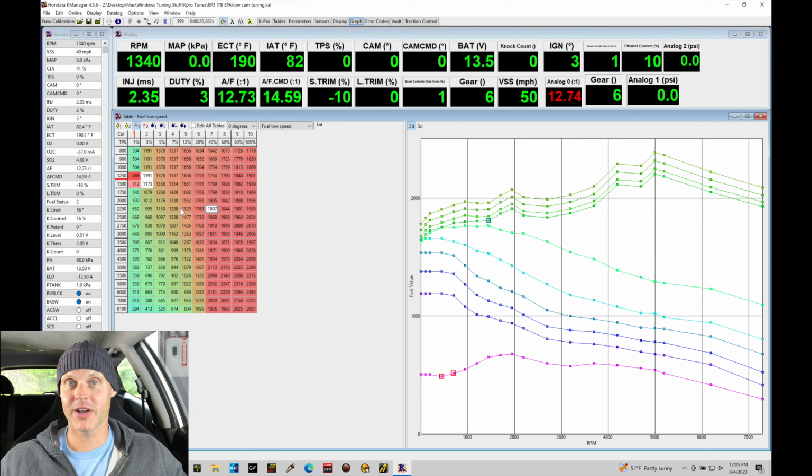Welcome back to our live training session here with our individual throttle body K24 swapped Civic Si. Now, in the last training module, we looked at the calibration process for our low cam, dialing in our cam composite blend table and getting everything 100% on the non-VTEC or low cam operation. In this tutorial, we're going to be working on our high cam. We're going to do some part throttle tuning, do our full throttle tuning, and do our variable cam blending for our high cam functionality.